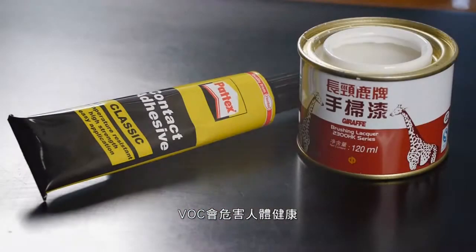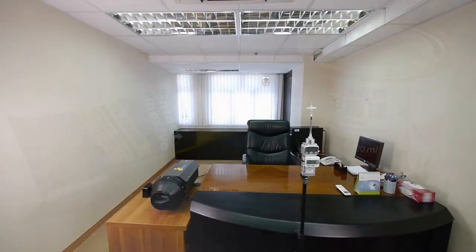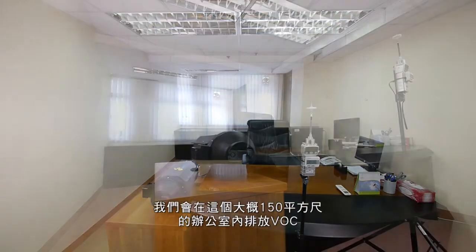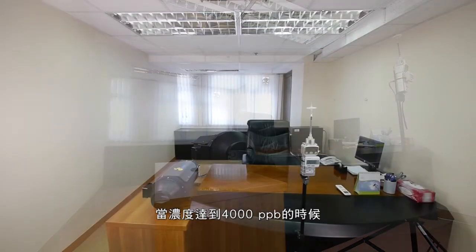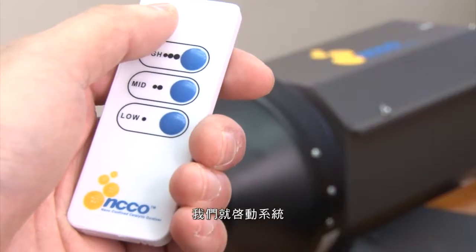Paint and furniture release volatile organic compounds, also known as VOCs. VOCs can be dangerous to human health, and some of them are odorless and colorless. We'll release VOCs in this approximately 150 square feet office and use a TVOC monitor to measure the TVOC concentration. When the concentration reaches 4,000 parts per billion, or ppb, we'll turn on the machine.